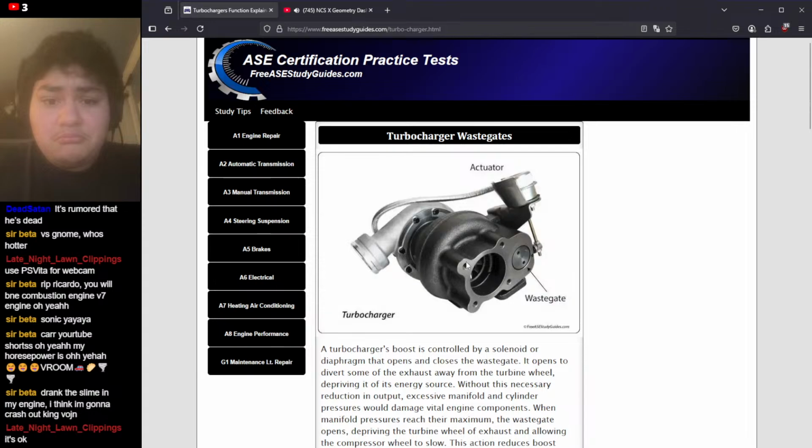I guess it makes more sense now, reading about it, but if you're not letting any excessive exhaust out, you're going to be constantly spinning the impeller, the turbine, and sucking in a lot of air, which then is going to cause the computer to dump more fuel, because you kind of have to, because if you run lean, your engine starts losing a lot of power and doesn't work right. You can start misfiring, and that's worse than running a lot of power.